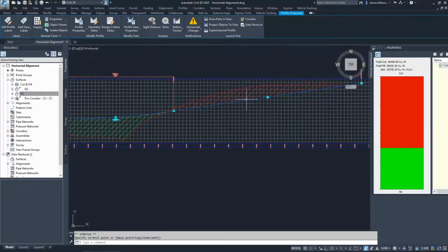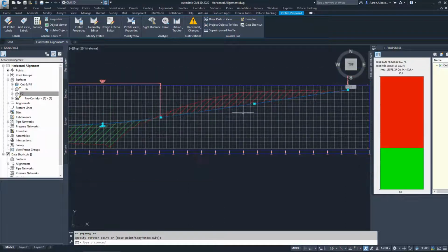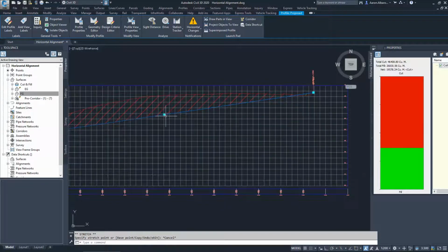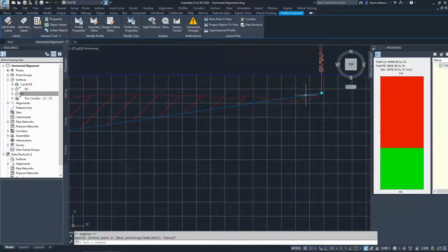Now I'd like just to make sure to draw your attention that moving this handle here, we shouldn't do that, mainly because if I do that, as you can see here, if you focus with me on the start or the end of the profile here, by moving this handle here, that's changing the height of the entire tangent. That means the starting and the ending point are changing. As we know, it's very important to keep this connection here between the proposed profile and the existing ground, otherwise that will create a large drop in our corridor, because we will have a small area.